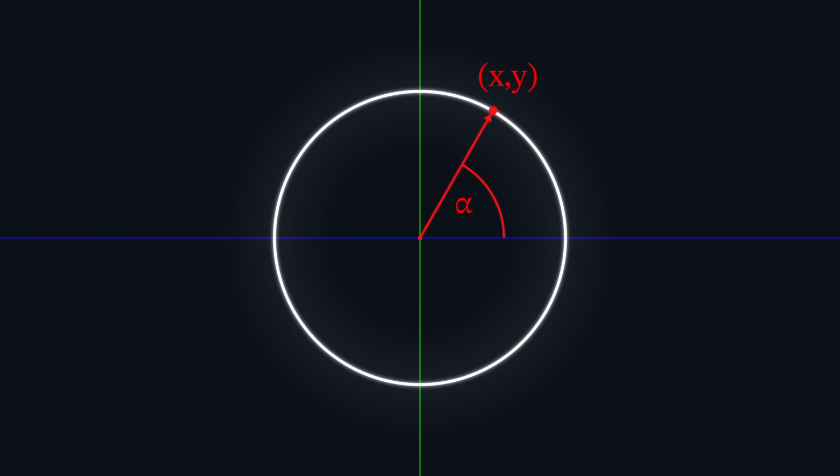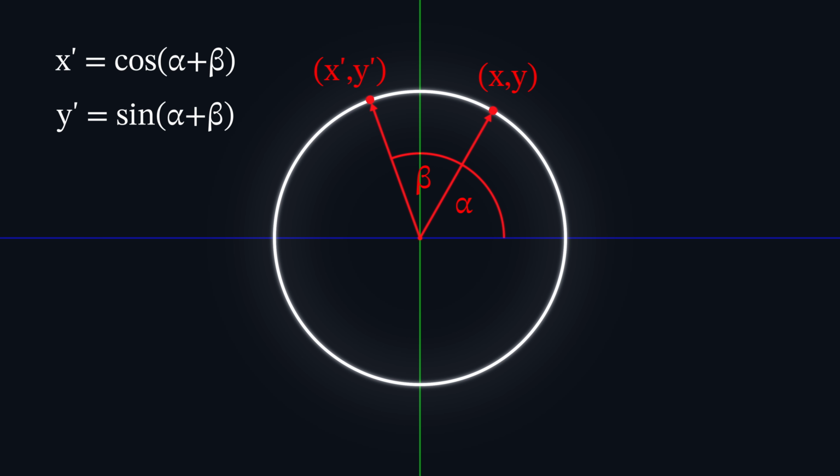But rotating our robot is a bit more interesting. Let's go back to the unit circle. If we take a point on the unit circle and add the angle beta to it, we get a new point that corresponds to the rotation of this directional vector by angle beta counterclockwise. So we don't need to come up with any complicated rotation procedure. We just need to add or subtract values to our angles depending on which way we want the robot to turn.